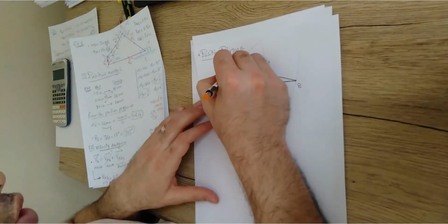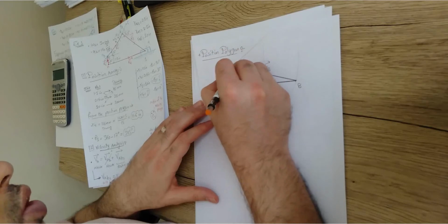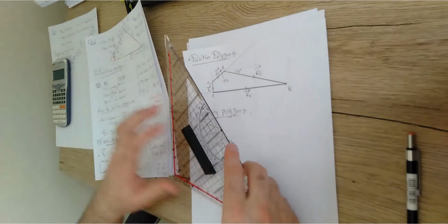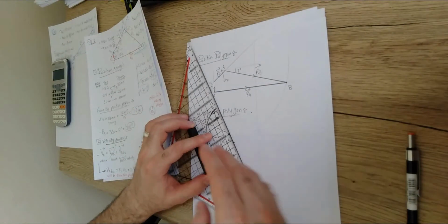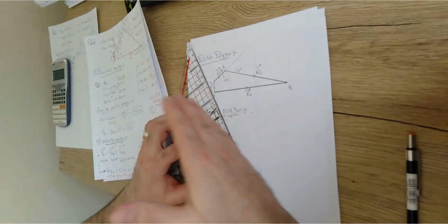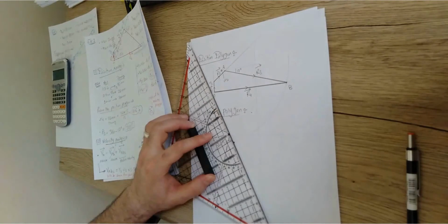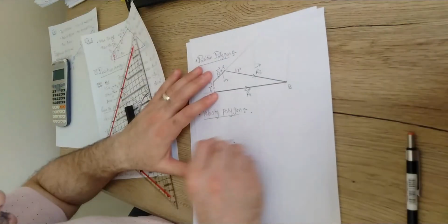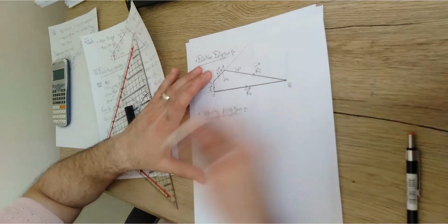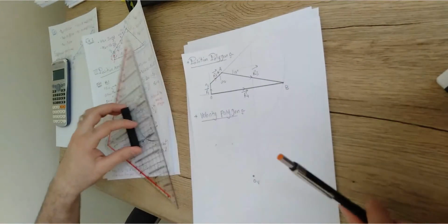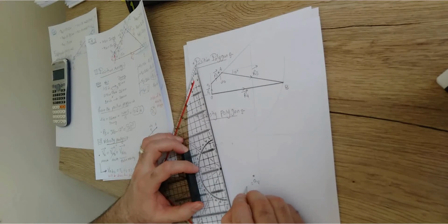So from this point, I'm going to draw a line, because omega 2 is going up. This is omega 2. This is the first step. From this point, I'm going to draw a line that is perpendicular to R2 and follows the direction of omega 2. It means that it should go up, with a length of 50. Since I'm using a big scale, I'm going to move this point OV a little bit down so I have more space, and this should be O2 and this should be the point O, right?